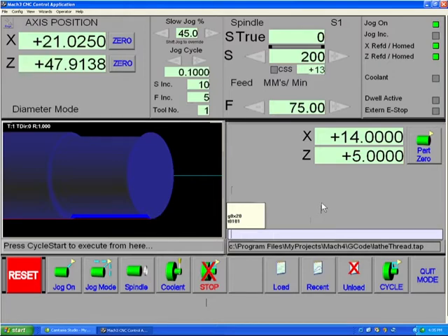It is possible to select offsets from other tool entries using any tool. So you could, for example, type T0105, which means use the offset from tool number 5, but use the other dimensions of tool number 1. That's an advanced usage, however, and for most new beginning users, and who else would be watching this video, you'll be using normally T0101 or T0202. So you're basically going to be duplicating the first two numbers on the second two numbers.